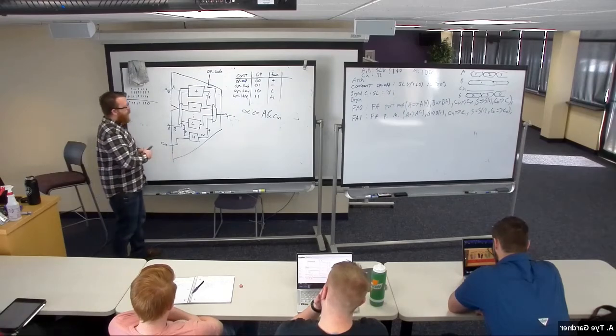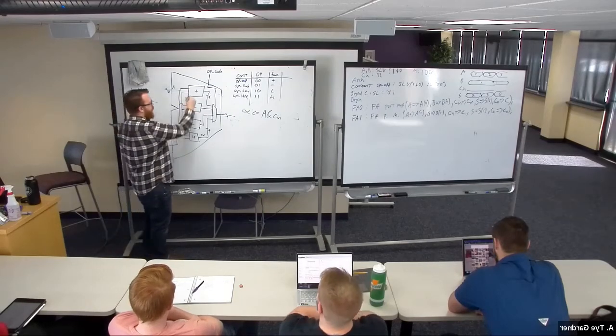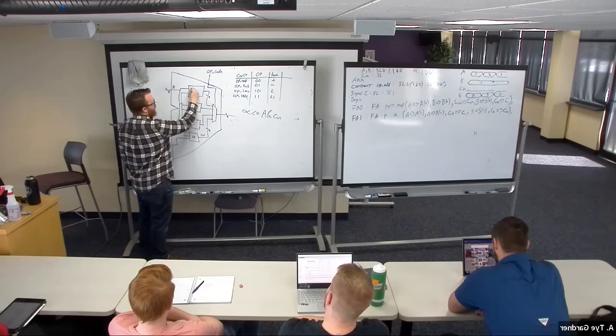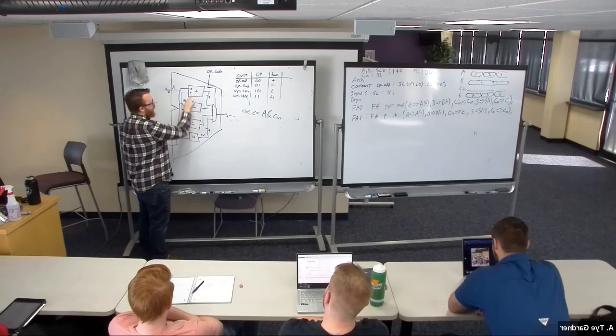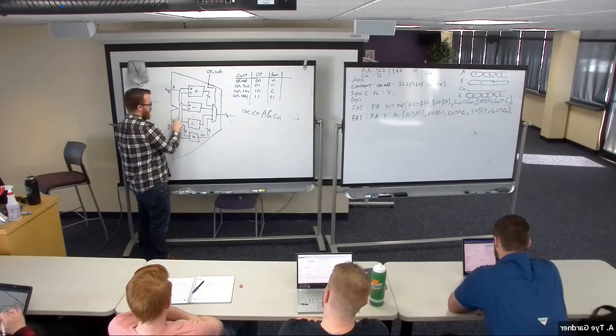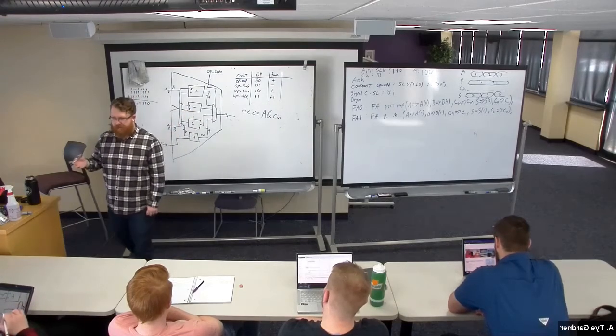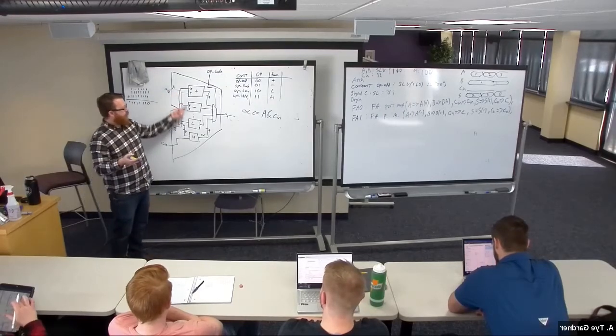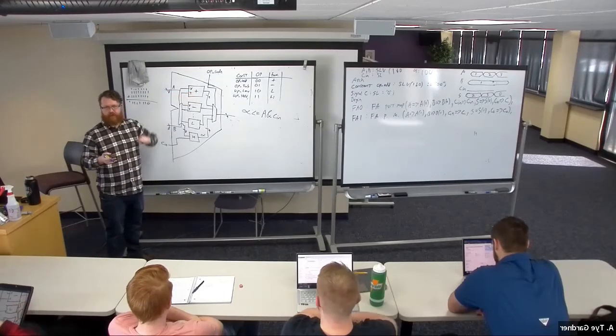So like the port map of plus, if this is X and this is Y, then X is getting mapped to A, Y is getting mapped to B. If I also call this X and this Y, same thing, X gets mapped to A, Y gets mapped to B. It's okay for multiple things to take the same signals as inputs.